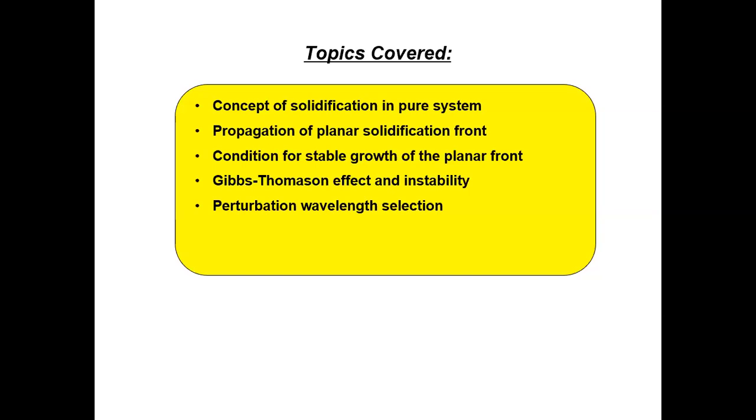Again, in these 2 lectures, I think you have a good understanding of the concept of solidification in a pure system, right? In this system, we just need to worry about how heat is taken away, because that's the only factor that possibly stops the solidification, right? When you convert some amount of liquid into solid, it generates heat, and the heat has to be taken away in order for the solidification to keep on going, right?